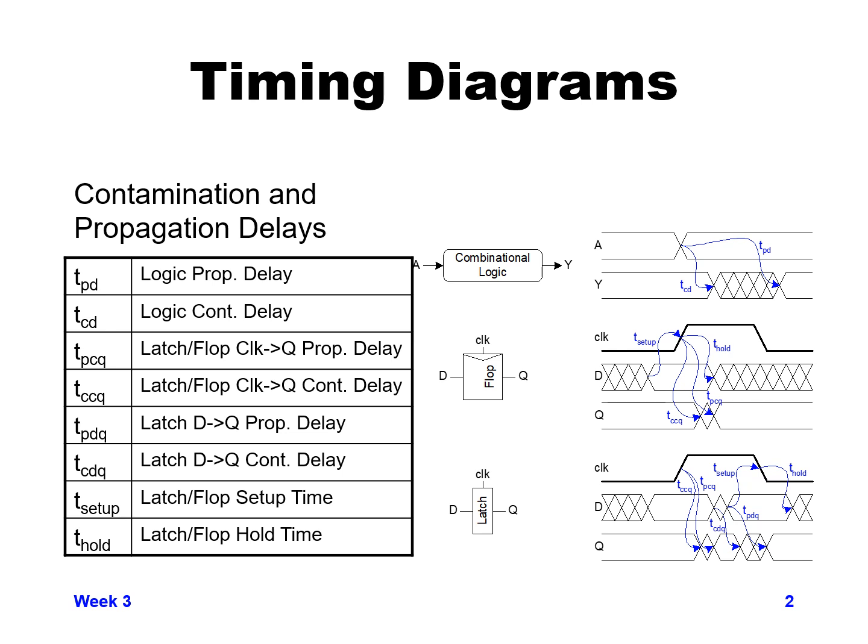Now we get to latch. Latch is probably the most complex one to examine because we have two different edges that we care about. When the clock edge rises, it opens the latch and allows a new value of data to go through. You can see on the diagram below, you get two things coming from the clock edge rising.